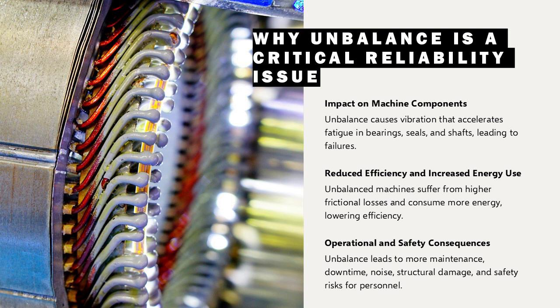safety. Persistent unbalance causes continuous vibration at running speed, which accelerates fatigue in rotating and stationary components. Bearings and seals are often the first components to suffer, leading to lubrication breakdown, overheating, and leakage. Shafts may experience cyclic bending stress, increasing the risk of cracks or catastrophic failure. Additionally, unbalance reduces machine efficiency by increasing frictional losses and energy consumption.